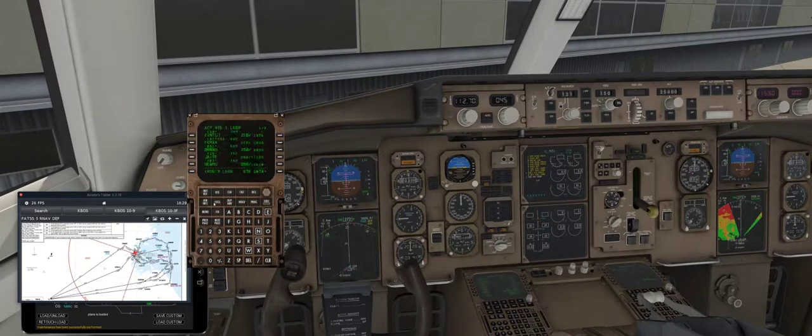But assuming you did, and you put in the departure, now you got some legs. The reason we didn't have any legs from KBOS to LGA is you'll see it's nothing but the departure from KBOS, and then we pick up the arrival to KLGA. There's not any specific navigation points between those. It's because it's such a short route. And we don't know yet what runway we're going to get, but we're going to go ahead and put the arrival in. We're still on departures.